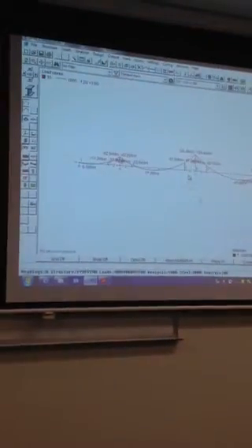Would that create confusion in the construction site? No, because you're going to separate your bottom reinforcement as one plan, and top reinforcement as another plan. So they'll put the bottom reinforcement in, and then they'll put the top reinforcement in. So they'll be looking at two different plans.